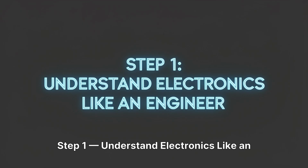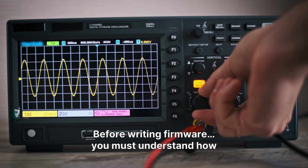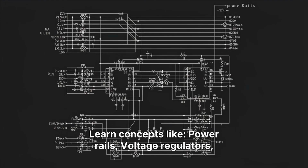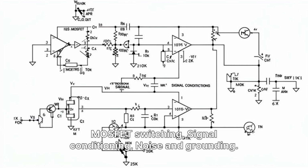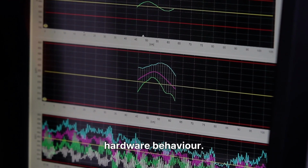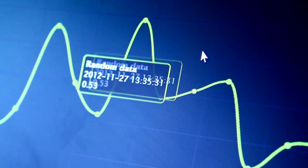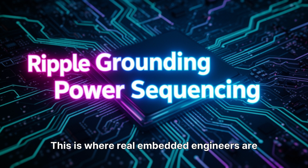Step 1. Understand electronics like an engineer, not a student. Before writing firmware, you must understand how current flows in a real circuit. Learn concepts like power rails, voltage regulators, pull up, pull down resistors, MOSFET switching, signal conditioning, noise and grounding. Because firmware engineers in production constantly debug hardware behavior. If your sensor gives wrong data, it is not always a software bug. Sometimes it is ripple, sometimes it is grounding, sometimes it is power sequencing. This is where real embedded engineers are different.